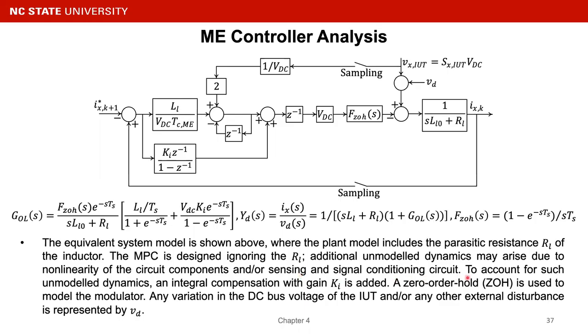To account for the unmodeled dynamics, an integral compensation with gain Ki is added in parallel with our model predictive control. A zero-order hold is used to model the modulator, and any variation of the DC bus voltage of the IGBT and any other external disturbance is represented by the disturbance term.